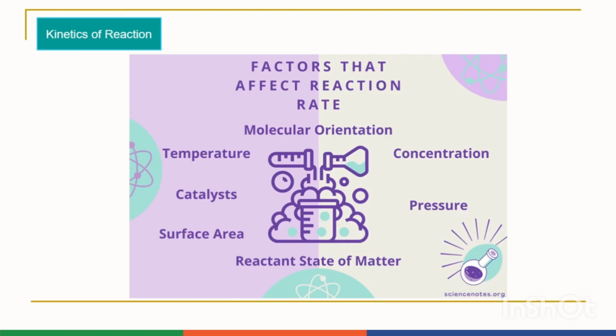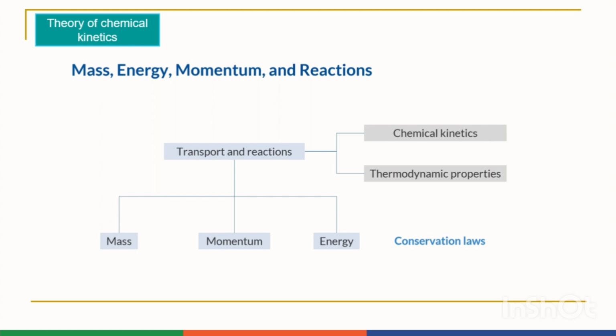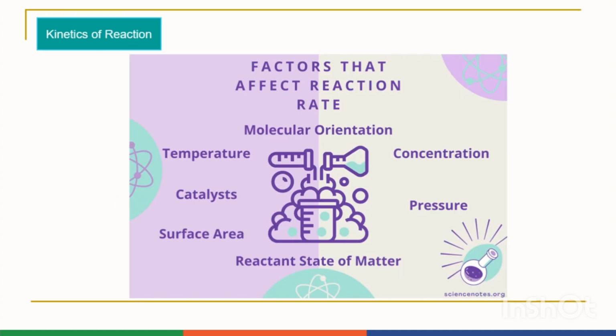Chemical reaction. Yes, to model a chemical reaction in Comsol software, you have to consider the chemical kinetics and thermodynamic properties. Chemical kinetics describes the rate of a chemical reaction that refers to the speed of reactant consumption or product production over time.